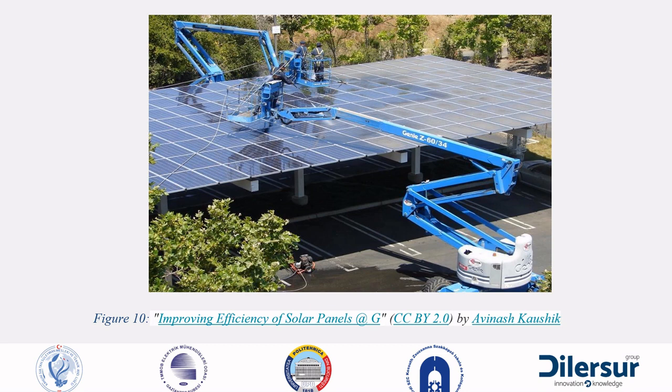Nearby obstructions, such as trees, buildings, chimneys, antennas, or poles. Self-shading from the adjacent solar panel rows. Horizon shading from the terrain surrounding the installation site. Other factors such as panel orientation or soiling. The main activities related to shade control are dealing with vegetation trimming and, when possible, the removal of other obstructions.